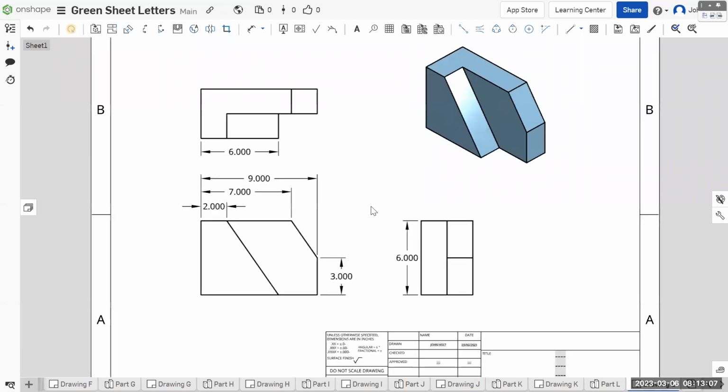Okay. And then depth front to back. First thing that happens is this, which is definitely the contour here. So we want to dimension it there as opposed to here. But we can actually beat this by dimensioning the reciprocal, the remainder. Either way, we're dimensioning the location of this edge from a known place. So that's fine. And then the only other depth is total depth, which is fine there also.